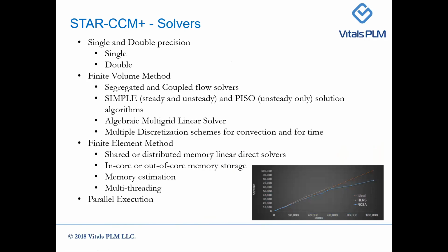Coming to the solvers, it comes with both single and double precision. It's a finite volume method, solving segregated and coupled flow solvers, SIMPLE and PISO solution algorithms, algebraic multi-grid linear solver, and multiple discretization schemes for convection and for time.